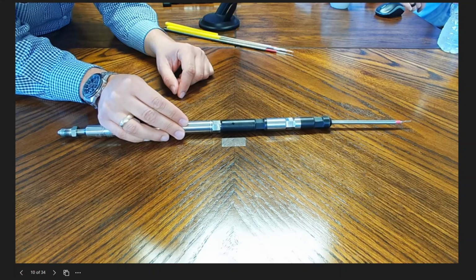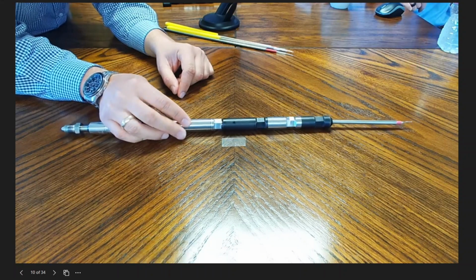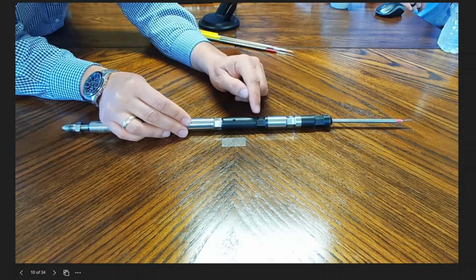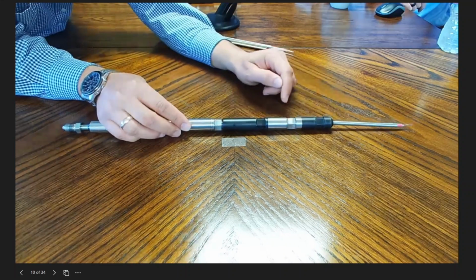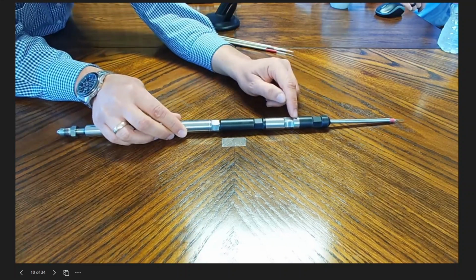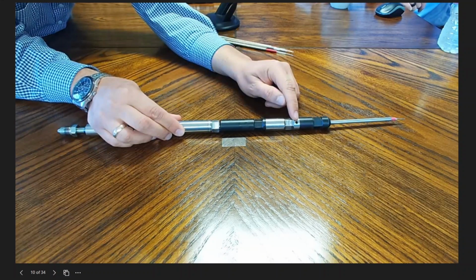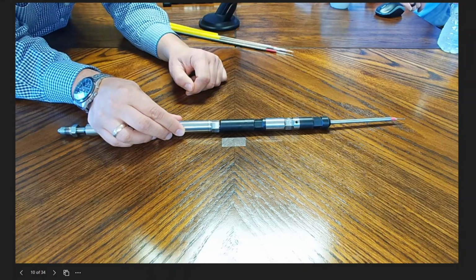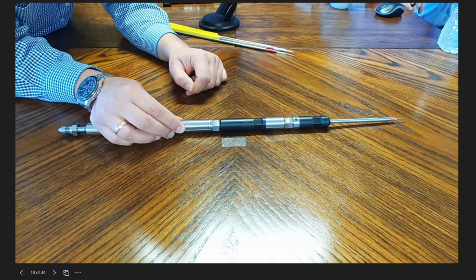And you could risk shorting the gauge out if you had a leak. Correct. So you pressure test this connection here, but when you make this cable head adapter to the TEC, you pressure test a second set of metal seals right here in this hole. Okay? And same thing, it's to prevent that fluid intrusion. What do you typically pressure test that cable head to?